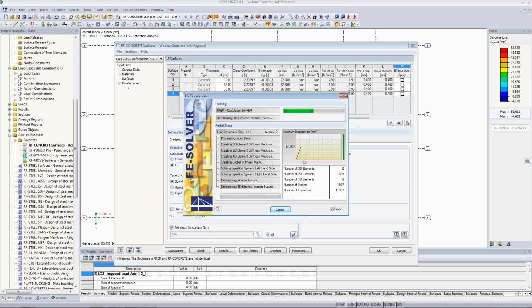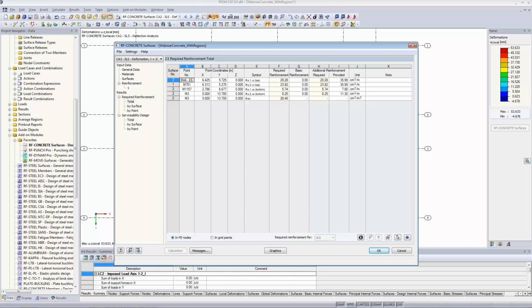Deflections that could damage adjacent parts of the structure should be limited. For the deflection after construction, the span over 500 is normally an appropriate limit for quasi-permanent loads. This is the next case, described in section 7.4.1 of the Eurocode.